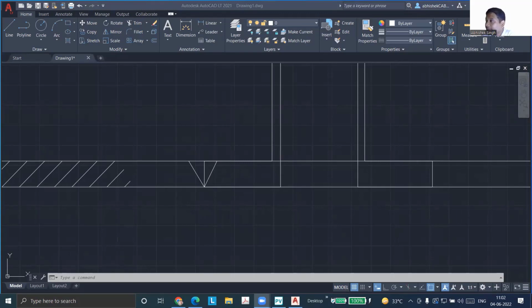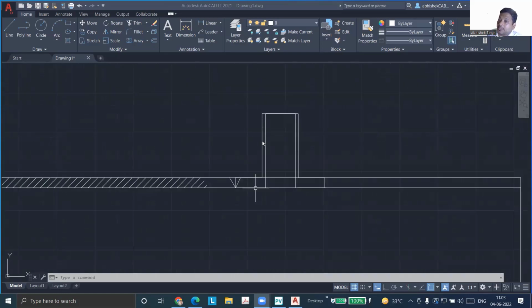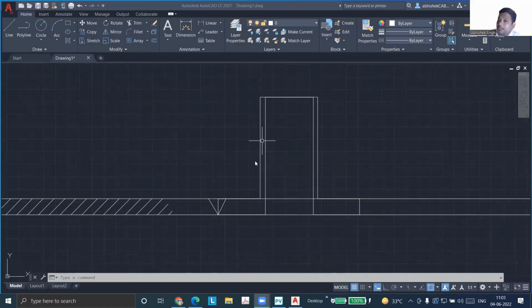Abhishek asks: here the shell thickness and the nozzle lip thickness, there may be variation, no? It cannot be one-to-one. Yes, but the thickness at the lip will be equal to the thickness of the shell, at the position where the nozzle neck thickness is starting from here. So the neck may be smaller.